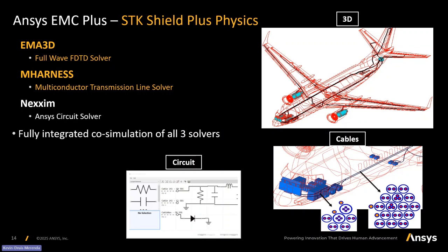So if you have a plane wave, for example, or a pulse or a lightning strike, we can inject current and voltages inside the system in ways that allow us to reproduce physical sources and how they interact with the structure. And then the more detailed aspect of the problem is when we have to handle how that electromagnetics, once it's inside the system, couples to harnesses or cables that will connect electronics. Because ultimately, we're trying to shield electronics from transients or frequencies that are too high, to be able to cause interference or even full failure of the device itself.